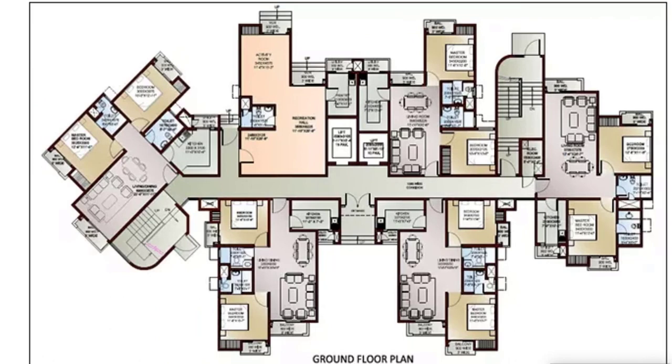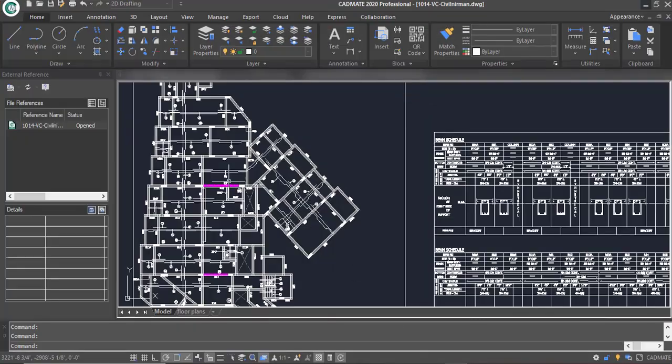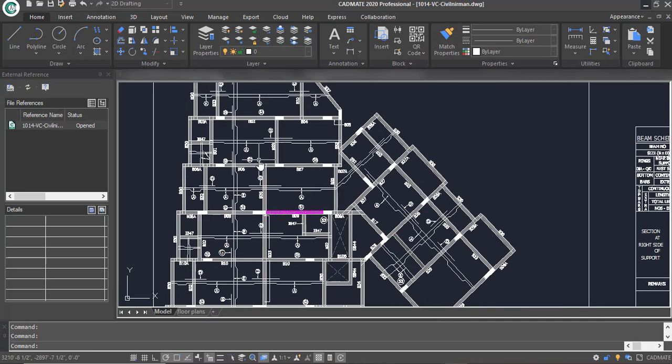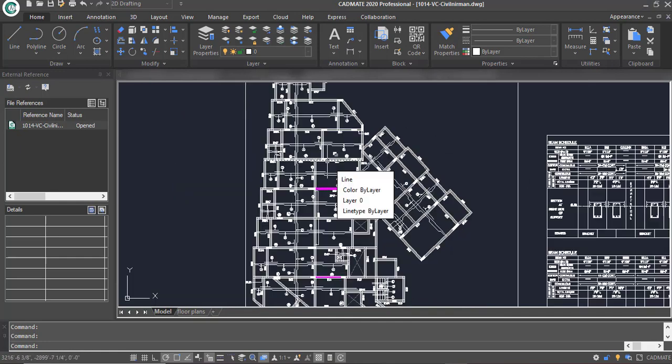They present useful information on the elements in the structure, such as the walls, concrete columns, beams, voids, floor slab, etc. I have just shown you one of the drawings for the slab over here, just to give you an idea. A typical structural drawing normally includes GAs for the foundation, floors, and roof. Here I have represented the slab drawing, but it can have the foundation drawings as well. Then section and elevation.